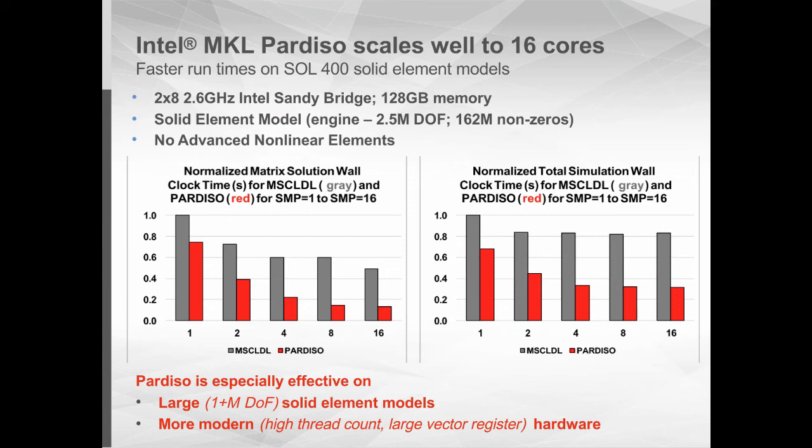That means the overall wall clock time is dominated actually by the matrix factorization. Advanced nonlinear elements in Solution 400 require a higher computational cost, and so by Amdahl's law, the factorization isn't as dominant as it would be for advanced nonlinear elements. The results on the left show the scalability of the matrix solve time using Pardiso, as well as our default solver called MSC LDL. MSC LDL is what you get in Solution 400 without specifying any solver with the sparse